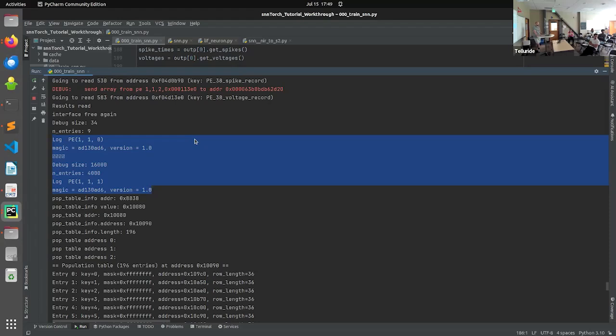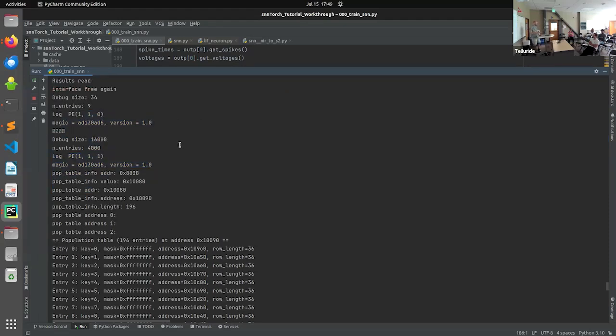And how does this transfer to SpiNNaker? If you do it on SNN Torch and then run the exact same thing on SpiNNaker, you've got 95% here, what might you get on SpiNNaker? I guess we'll see in a second. No, because it's just a random input, just to see the flow really. It's basically a floating point operation on the processor, and your standard way to execute SNNs on SpiNNaker is also using floating point. On the ARM cores, you have floating point instructions, and since it's floating point on the host and floating point on the chip, you should not have a difference there.